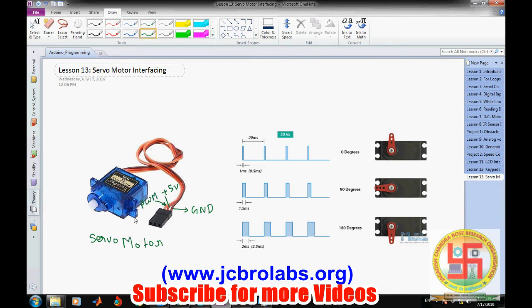Okay, so this angular motion, like how much angle we want to rotate this servo motor, depends on the PWM wave or the duty cycle of PWM, right? That means pulse width modulation. Generally in order to rotate this servo motor, we need to apply pulses at a frequency of 50 hertz. If it is 50 hertz, from here we can find the time duration of the pulse as well.